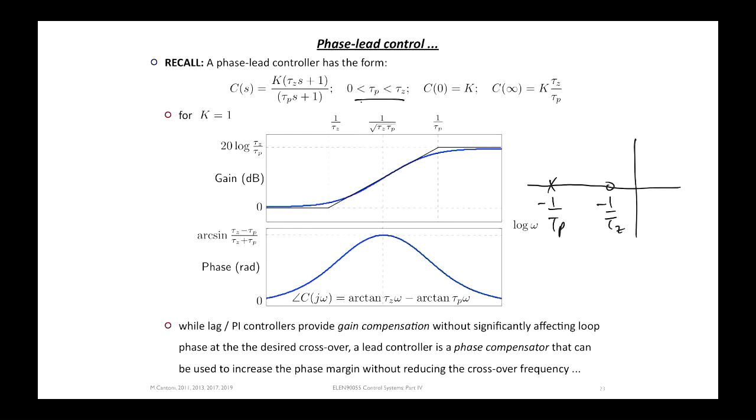All right, and you can see that what a phase lead compensator does is it adds positive phase to the open loop transfer function, right? And if you line up where it's adding positive phase to around the desired crossover frequency, which relates to the transient type specifications that might come with the problem, then we can use it to improve the phase margin to push you up away from minus 180 degrees, right?